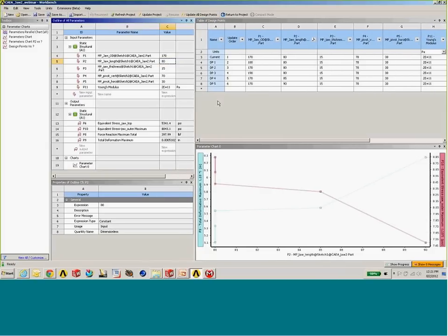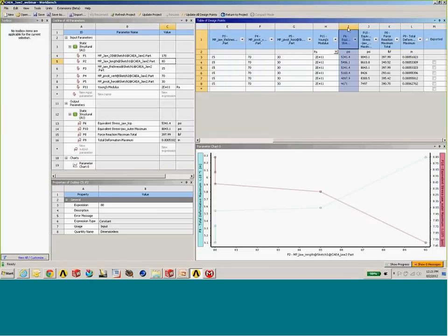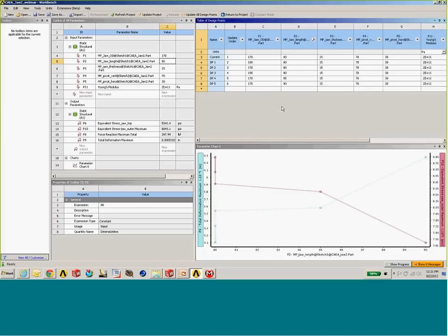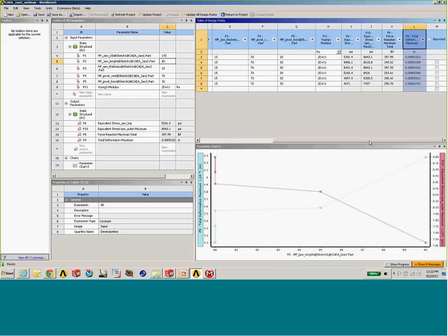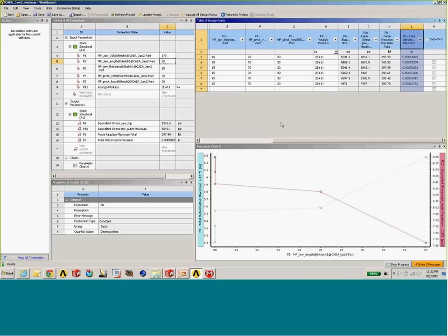But I may also want to look at a table of design points. So over in the upper right-hand column, we'll see a table. We'll have our input quantities listed as the first columns, and that will be followed by the output quantities listed as well in this table. I can freely go in now and start to add in different design points that I would like to evaluate. If I happen to have a table of these design points from some specification and it's in something like cell form or table form, I can paste those into my design table right now and kick off a manual design study or just a regeneration of these points and tracking the output or the response of the system to changes in the input.